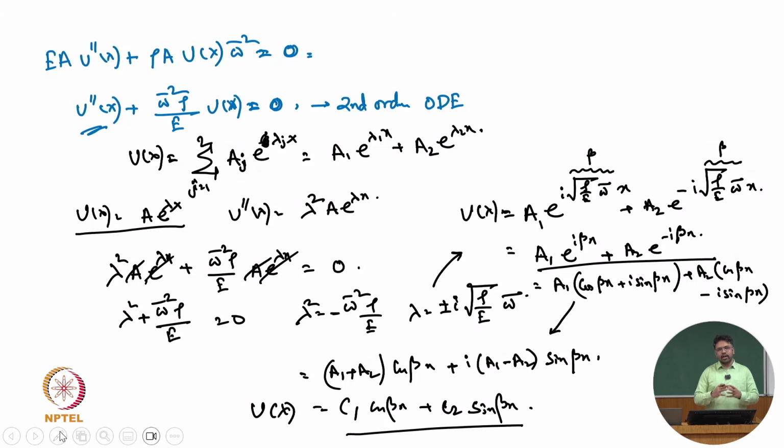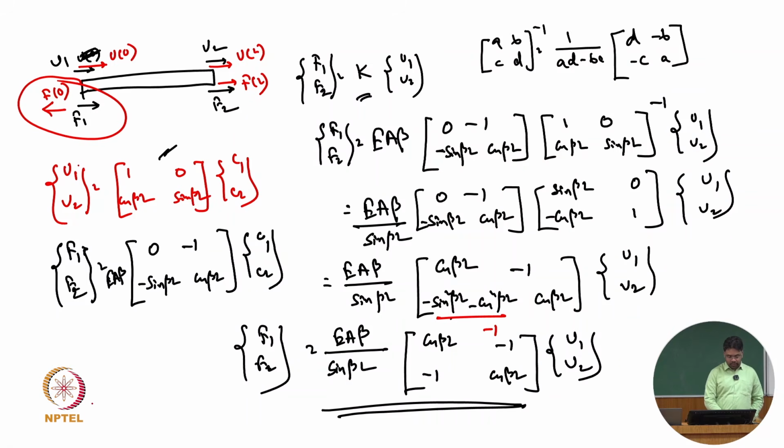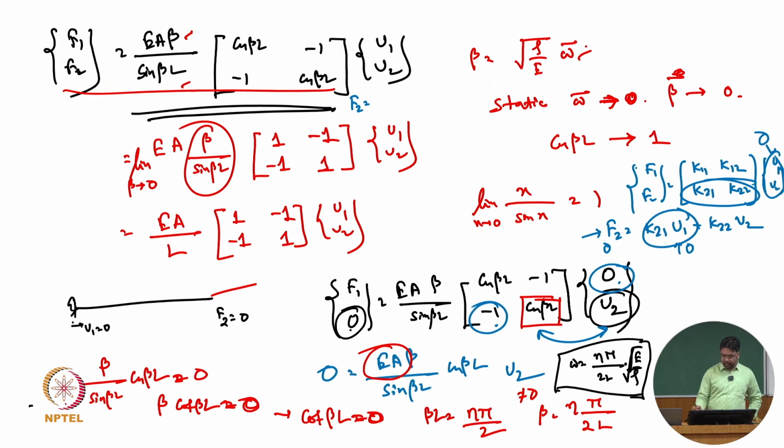That's a very basic form of a continuum element, and you have seen that we first found the equation for the displacement field, then we formulated from there the stiffness matrix, and further we saw how the dynamic stiffness matrix or the spectral element matrix can be correlated with the static stiffness matrix if we calculate it for very low frequencies, like omega tends to 0.